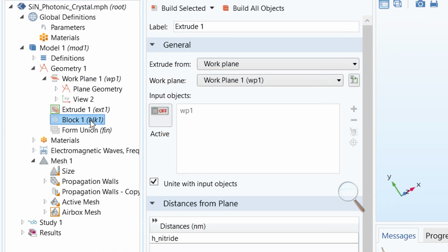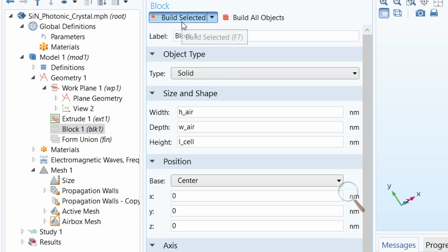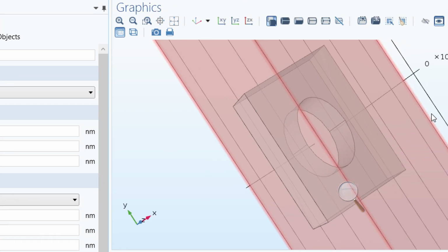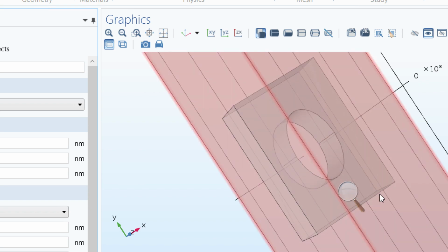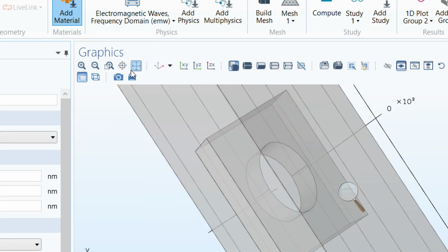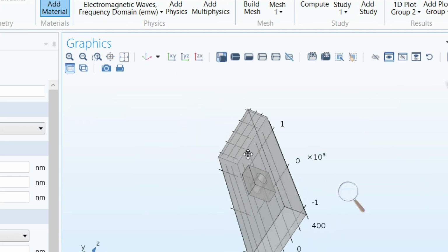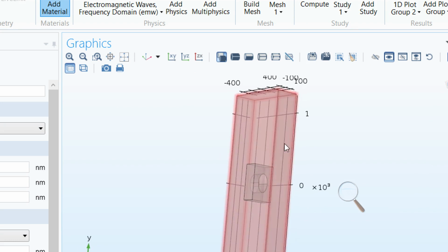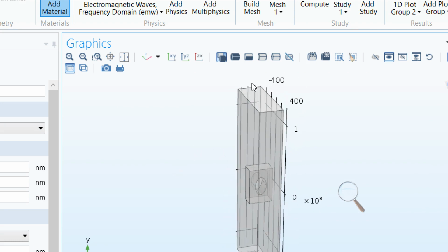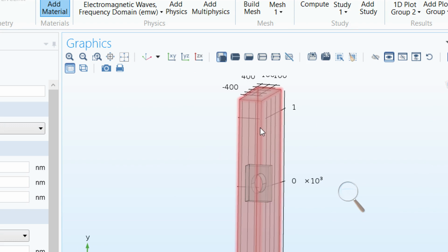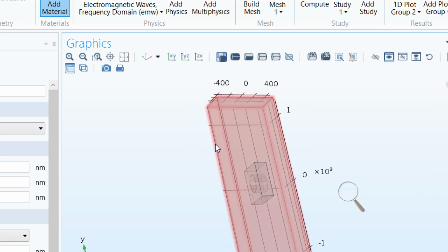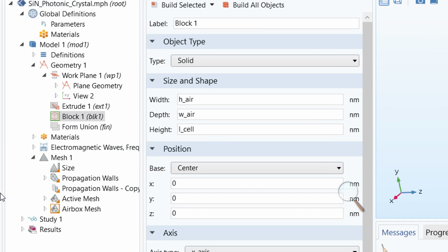Then I draw a box around it, which I usually call an air box, or maybe in this model not. You see it's around your structure. So Simon, coming back to your question, for this surface around your structure, where the light can go on and on, we just put PEC to stop the simulation at this point. But for these faces, we will put Floquet boundary conditions. All right?